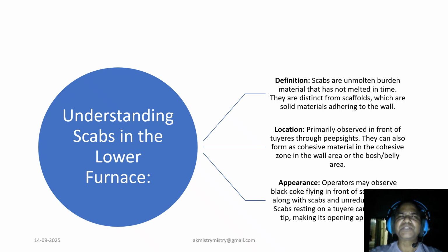Additionally, differential pressure delta P over the tuyere stock can signal blockages, and monitoring stave temperature can indicate localized cooling due to adherence. So, if the tuyere physical look or the cameras signal something like that, we can correlate with the stave temperatures also to corroborate the findings.